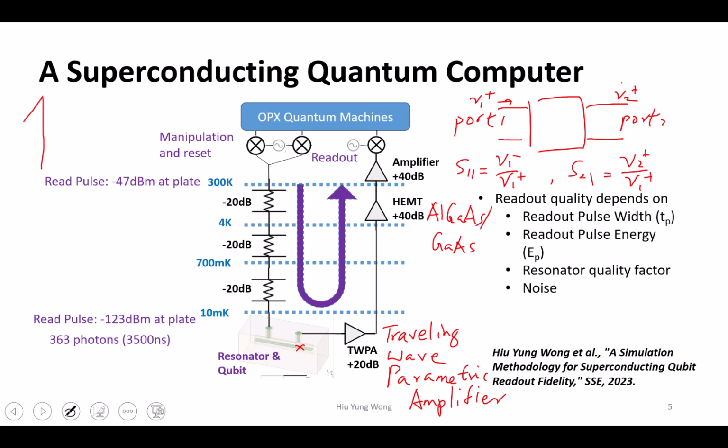Remember, at that time we talked about this band structure. So this is a narrower band gap, gallium arsenide, right? And this may be a higher band gap, aluminum gallium arsenide. This is an alloy. Again, a smaller atom has a larger band gap. And you have this electron confined in this direction. Going into the screen is the direction of transport. The source is at you, and then the drain is inside the screen, right? The electron is flowing perpendicularly in this direction.